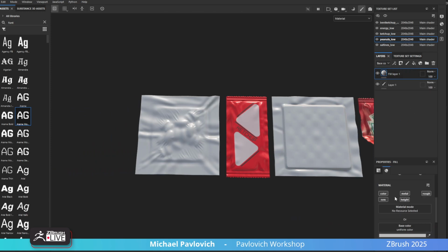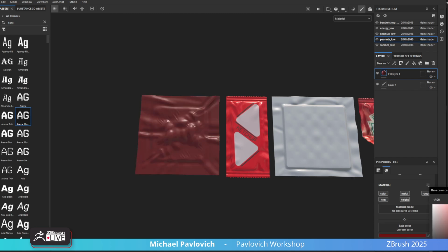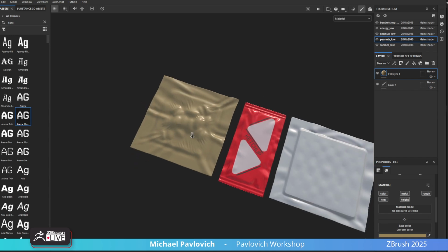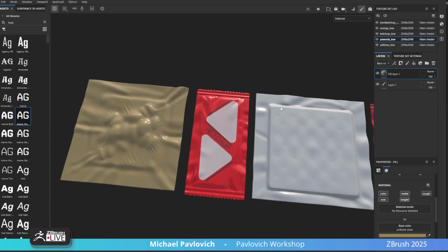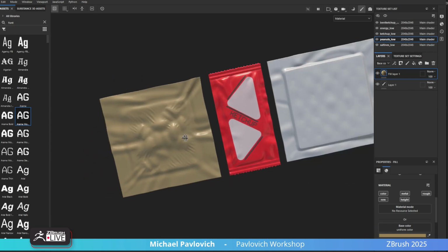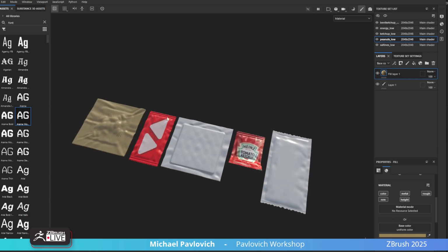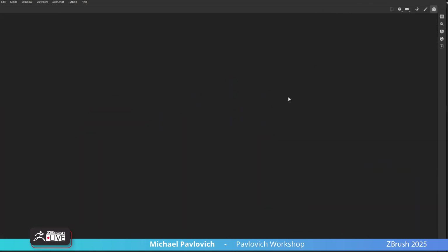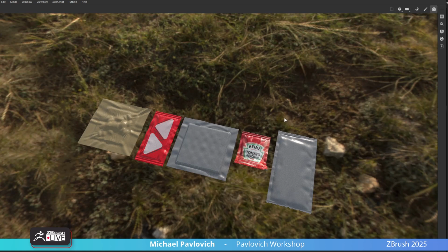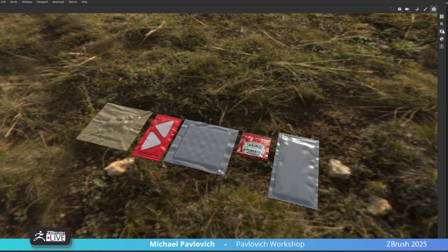These ones look pretty plain. I wanted to say it was like a tan or whatever. And if you want to make it grungy or something, you throw on dirt. You can go through here and stamp text. You can make outlines and stuff like that. So we have that. And then if you want to render it, you can just throw it in here in iRay. And let's switch some settings here.